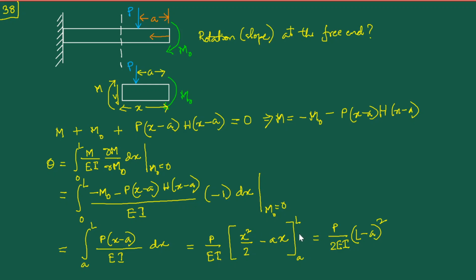So on that note, we have learned two important concepts here. One regarding the introduction of fictitious forces or couples, and the other regarding the use of the corollary to Castigliano's theorem on deflections, such as to say that it is something like the Castigliano's theorem on slopes using the moment.